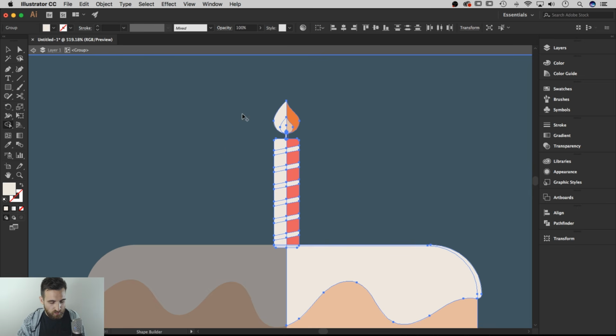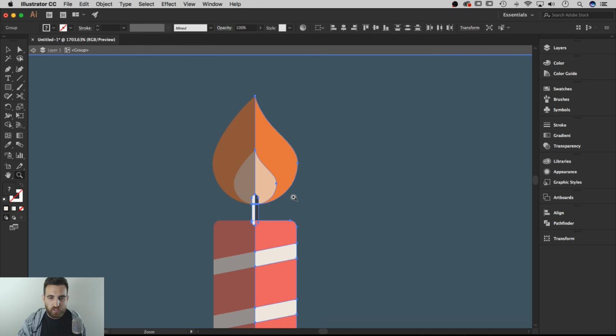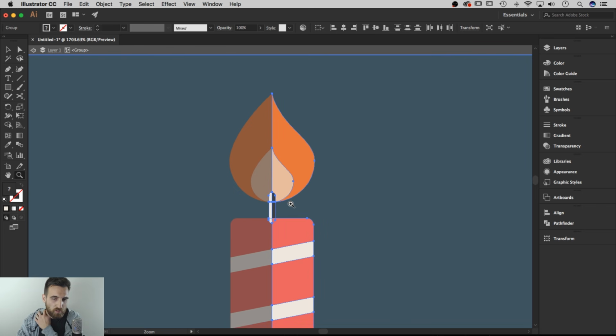Shift M and then hold Option and draw through all the shapes that we don't want. Now, there's a couple more in here, so let's zoom in here again. That's a shortcut key Z for the zoom tool. And you may have a scrubby zoom, or you may have the zoom to selection like I'm showing you right now, where you just draw and it zooms to that.